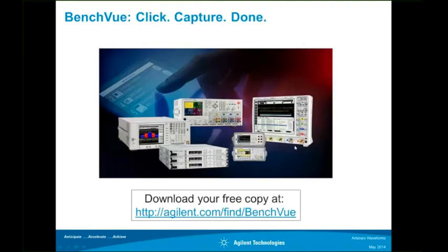So hopefully that's of use to you guys. I don't know how often you capture signals from your DUT, but that is one of the main features of having an arbitrary generator with a scope. So you can simulate your signals and change parameters very easily with that tool. And hopefully I just showed you that you can do it within less than 10 seconds.